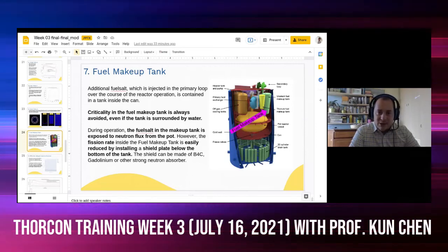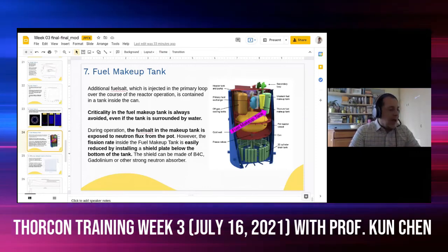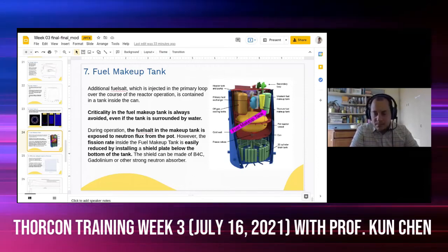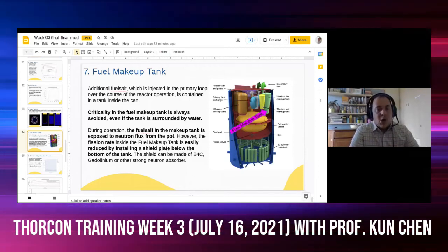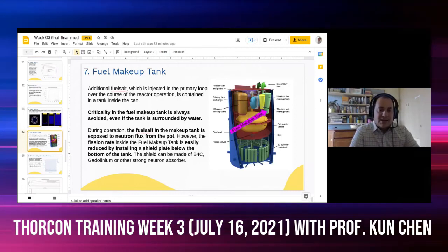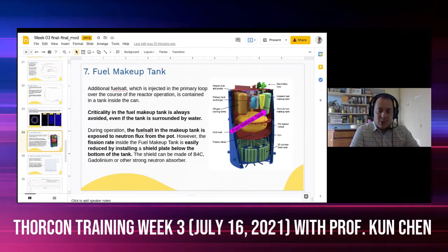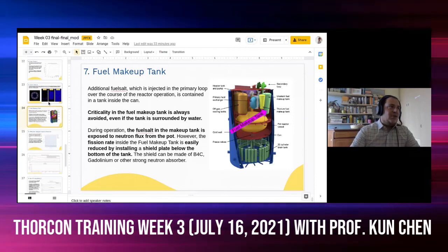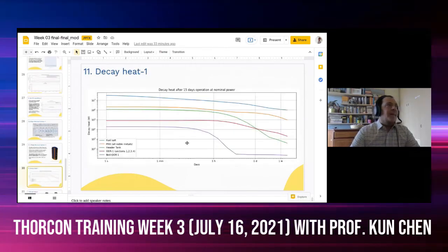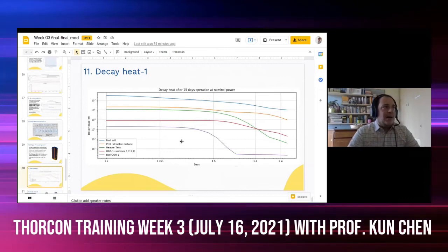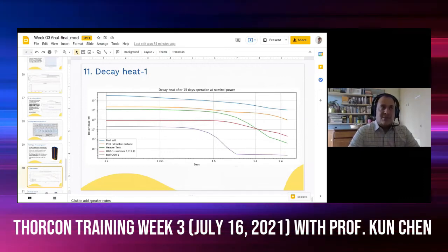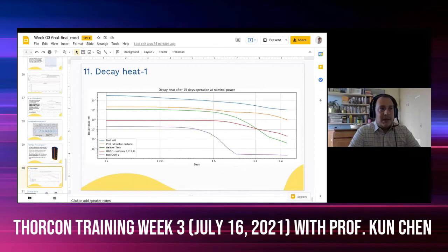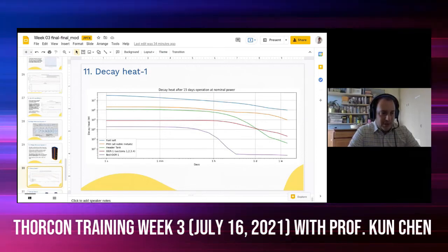That is to be taken into account during nominal operation. It doesn't have an extremely large impact, but it has to be taken into account. On top of that, in case of accident, those noble metals fission products are a source of decay heat in the primary heat exchanger, which might amount up to 1 megawatt of decay heat in the first minutes after the reactor shutdown. So that plays some role. I don't know if this answers the question.